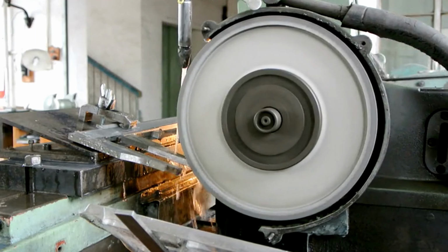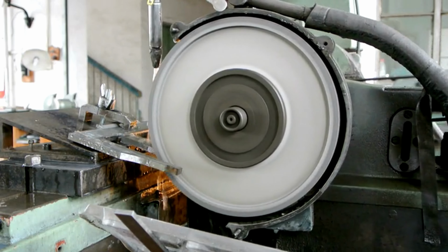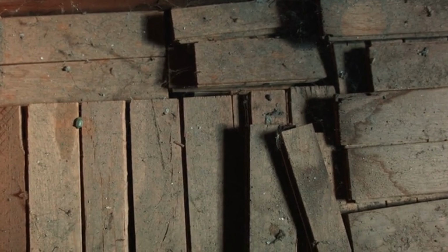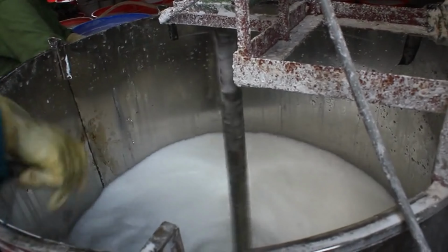Cleaning and screening. Centrifuges remove heavy particles, for example, sand, metal. Fine screens filter out undissolved wood fragments. 4. Bleaching for white paper. Bleaching removes residual lignin and impurities to produce whiter pulp.